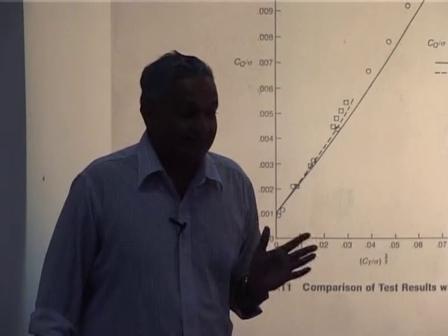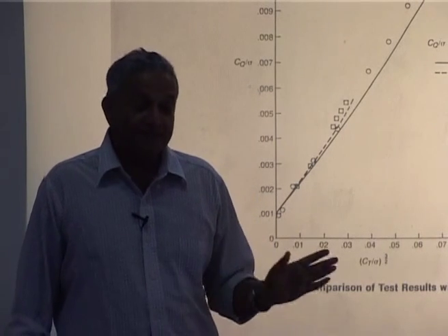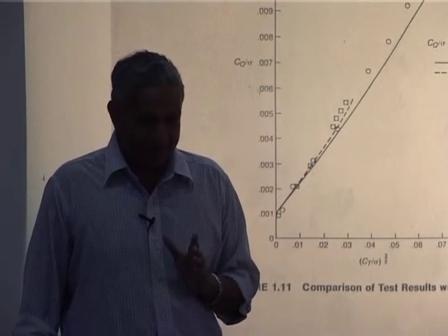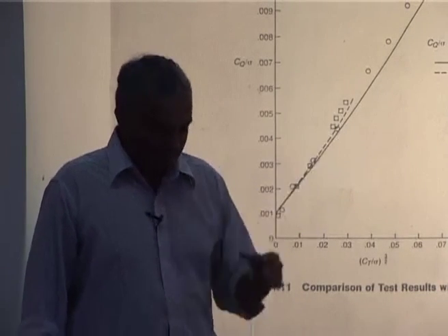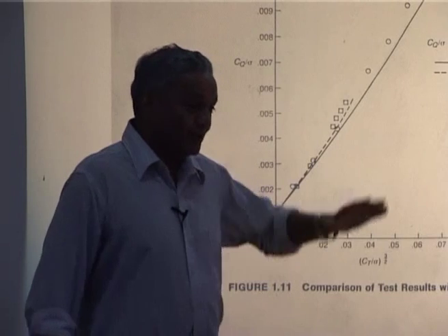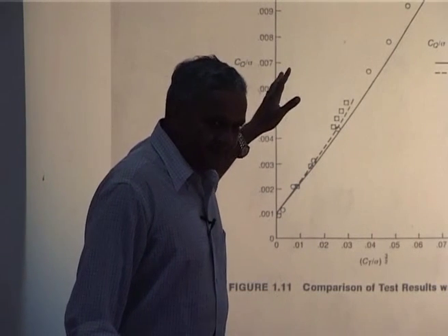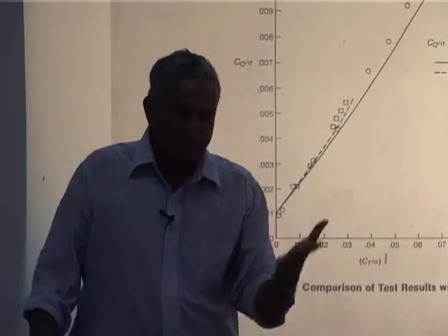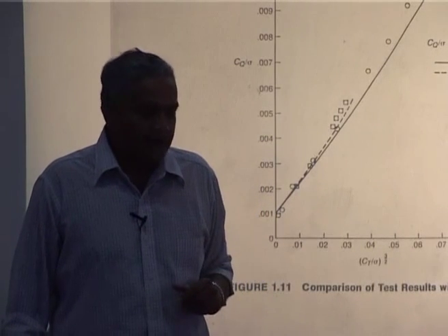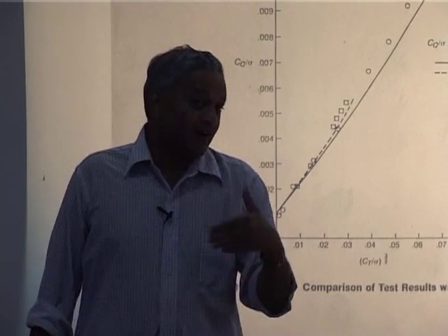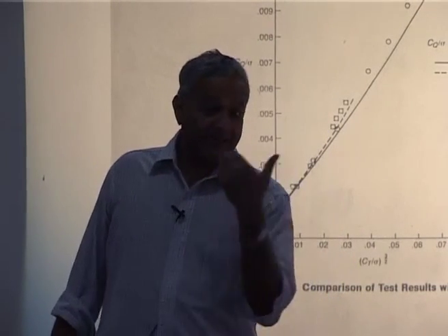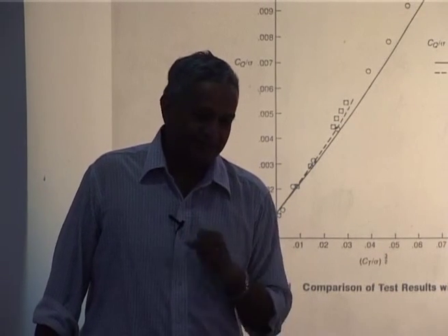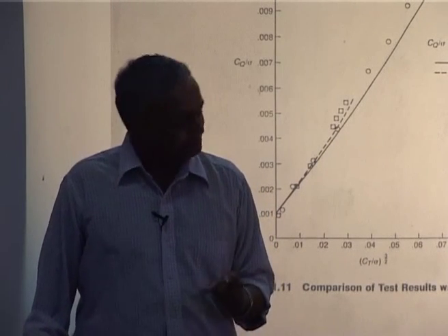it is not restricted by power, it is actually restricted by the fact that suddenly vibration will increase at some speed. Beyond that, you have to sit in a helicopter to see the vibration. I am telling you, the noise will go up, pitch link load will go up, the pilot will find it difficult to control. Even though I have power in my engine, please understand, I cannot take the vehicle beyond, because I can't control the vehicle, the vibration is very heavy. So what sets the limit is not the engine power, it is other characteristics that really set the limit of your helicopter. You follow?